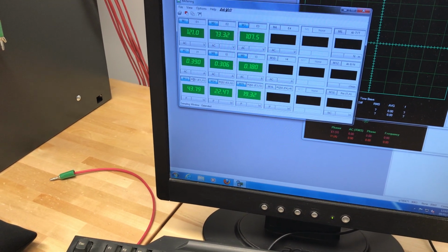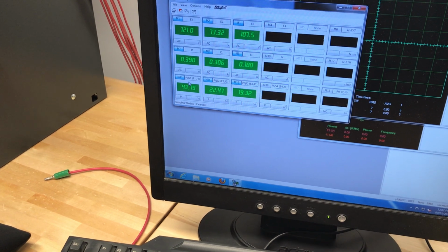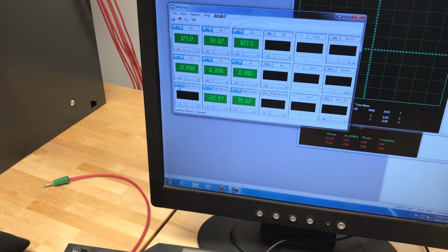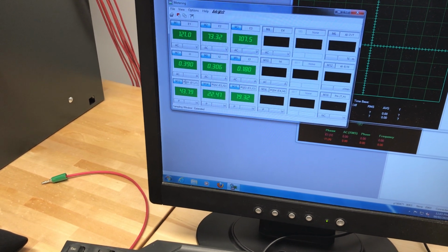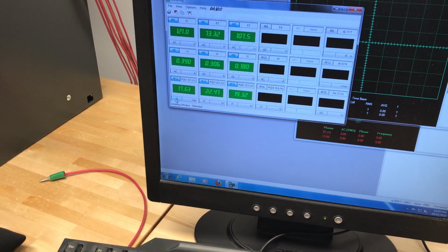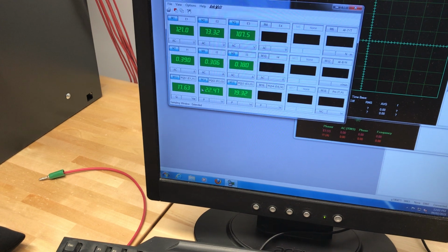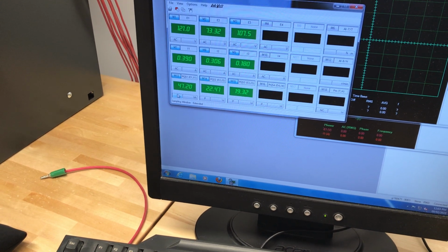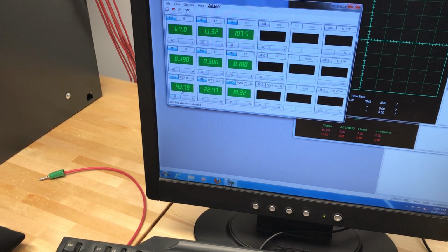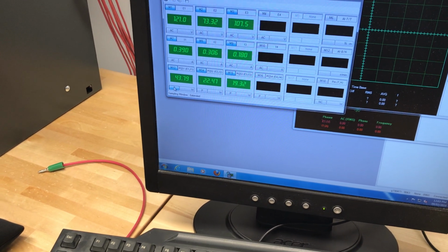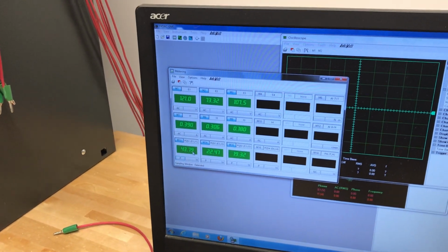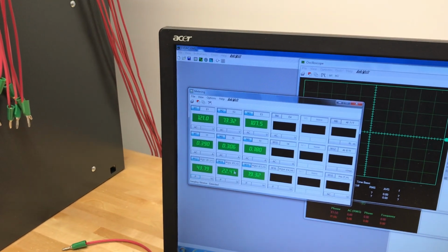Like what you are seeing here, this is measuring the power. I can measure the power, active or reactive. Here, if I click on this, it will measure the power P, but if I click here on P, it will give me Q. So what I'm reading here is Q. Click again, it's giving S. Click again, it's giving back P. So by changing here, whichever power you are looking for, here I'm reading P coming from the source.